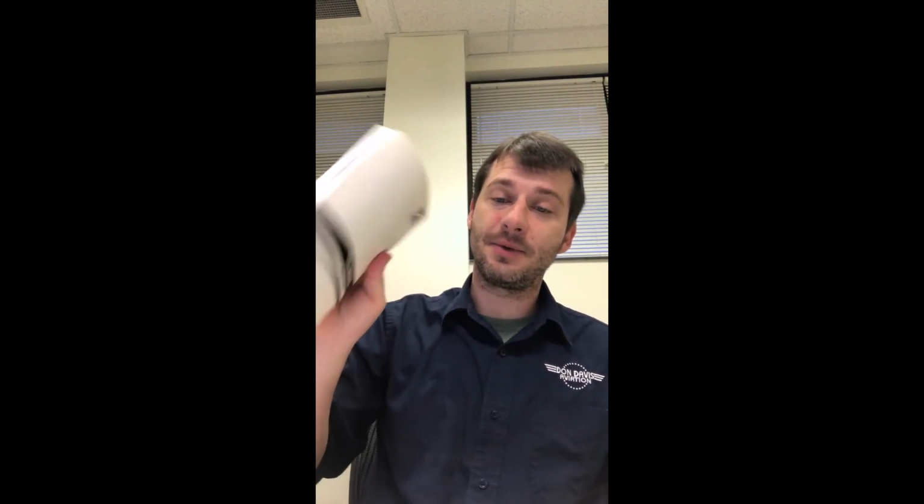So we are going to take into account some of those other performance factors we talked about. We're not just going to do that simplified point A to point B calculation that we did last time. We're going to have to get into the performance manuals. For this one, we're going to be using the Cessna 172S manual, section 5, the performance section. And like we talked about in that PowerPoint slide, Cessna does give them to us in tabular format. So they're going to be a little easier to run than the spaghetti charts that Diamond gives us. However, we are going to have to do a little bit of interpolation for those charts,